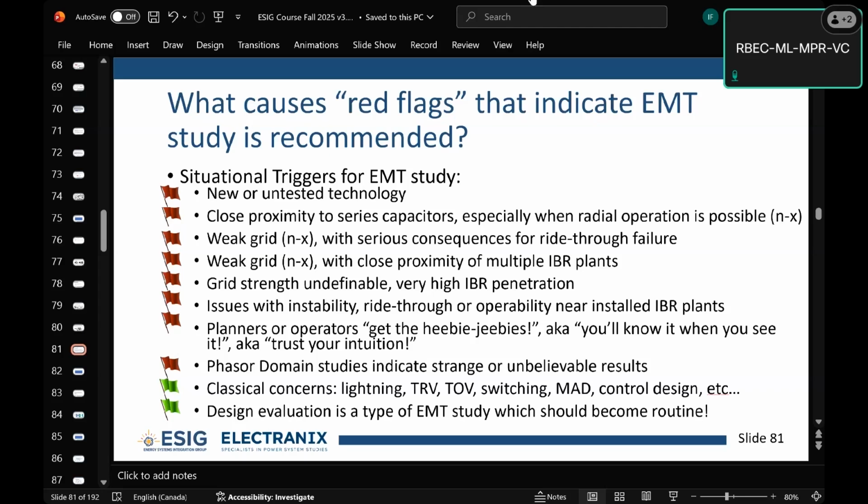A good example is transmission line modeling, because you sometimes have very, very complex rights of way coming into a station. You have mutual coupling between different lines, sometimes multiple circuits on a tower, and all of that changes the sequence impedances of the system, and changes the mutual coupling and the induced voltages on one phase from the other. All of that gets overwhelming, and the lines can be very difficult to model. It can take you a week to model a right of way. Do you need to do that?